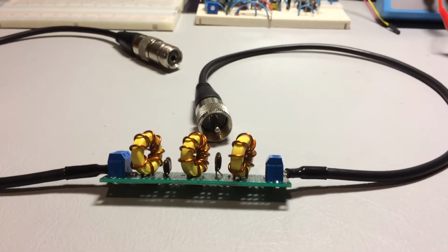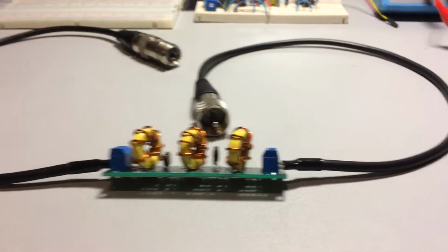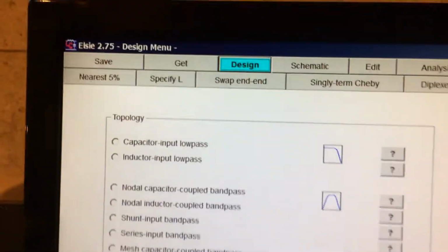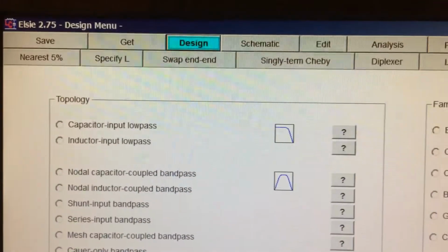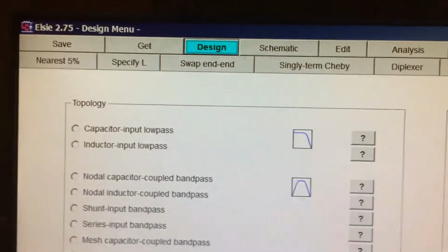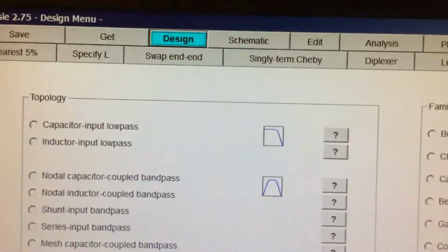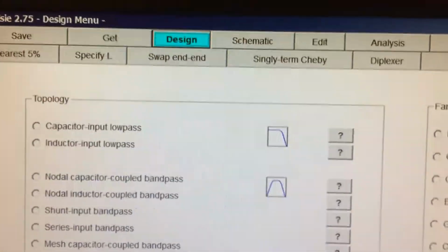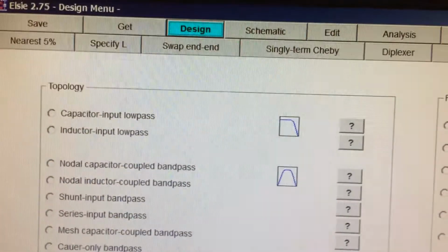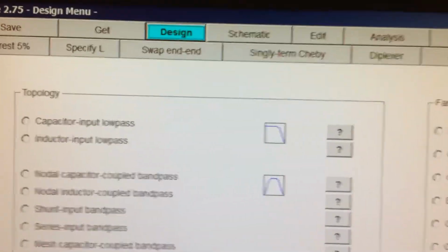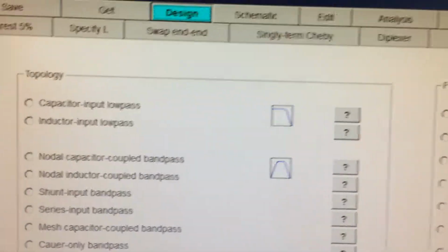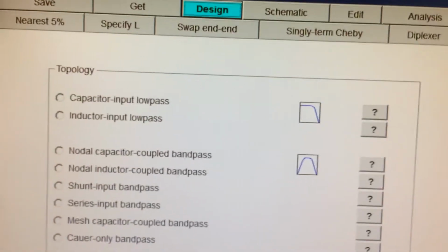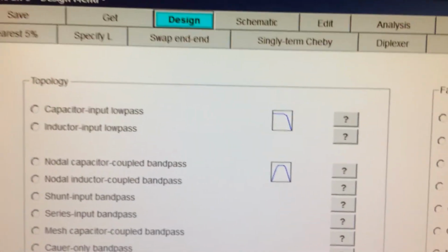And you do a quick count there, you see 5 components. Okay, so this filter has 5 poles, typically referred to as a 5th order filter. So an LC filter that has 2 poles, typically an L network, would basically be a 2nd order filter. This particular filter here that has 5 components is a 5th order filter. If you design one with 7 components, that's a 7th order filter.